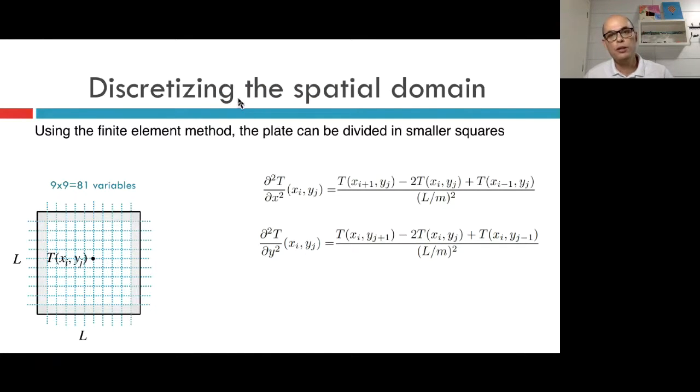Well, the first task here is to discretize our spatial domain, which means that our derivatives can be written in a discrete way, in this way. There are higher orders that will be neglected here. The physical system we are considering is this plate with size L, and we split this domain into 11 small cells along the X and Y directions.